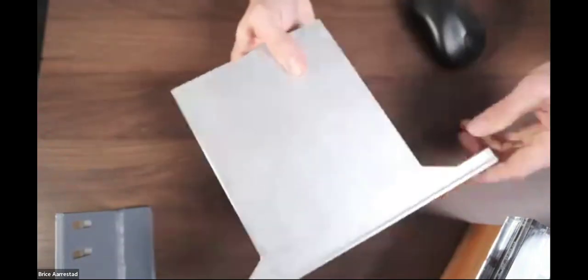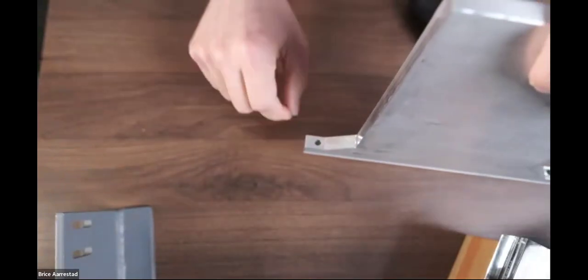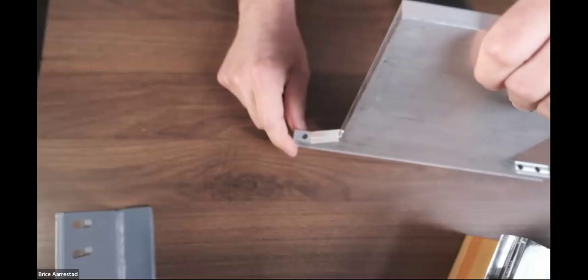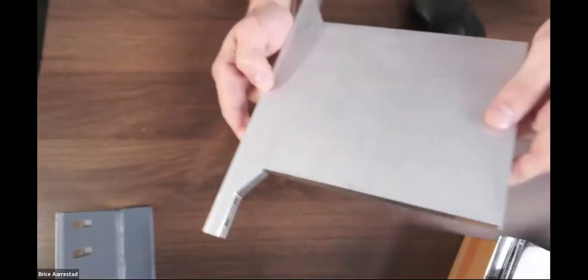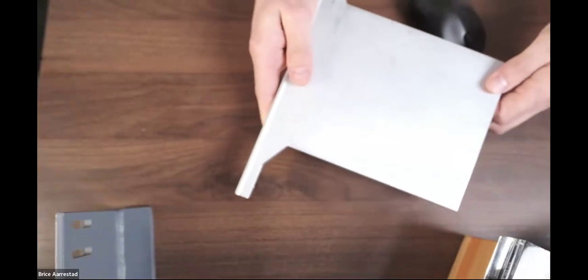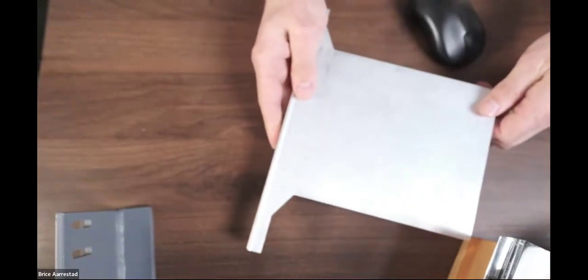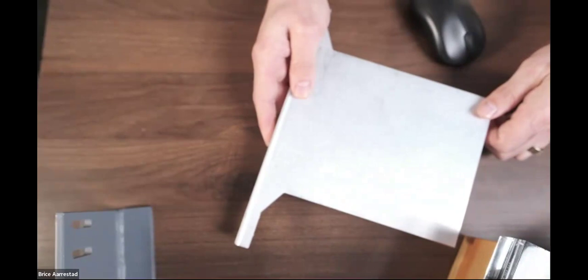Another option that we're showing here as well is a knife plate. This one is a little beefier. This is an aluminum plate that gets screwed through these holes here into the back member. And one of the benefits of using a timber curtain wall system is, again, you're screwing into wood. So any of the thermal bridging issues that are inherent with using an aluminum system are taken away. Those concerns are alleviated. Oftentimes we provide the plate, and then a glazing installer will drill attachment points to it for an exterior fin or a solar shading device, solar panel device, connecting into that.